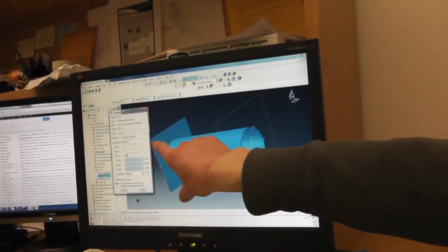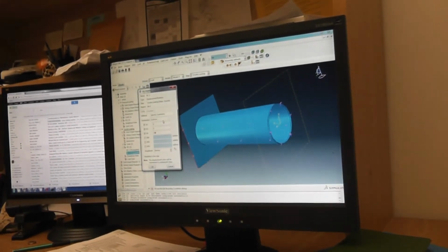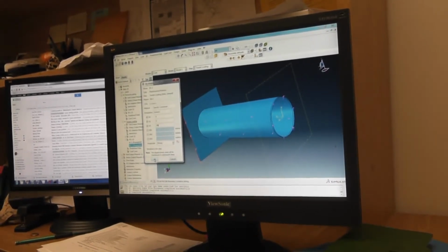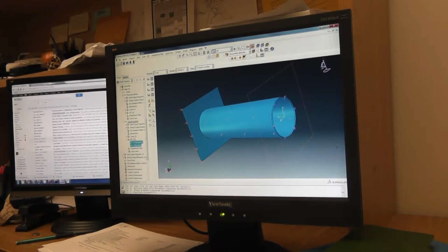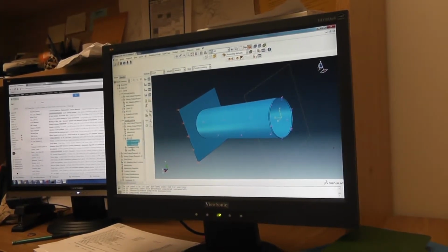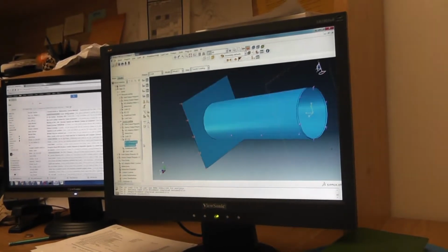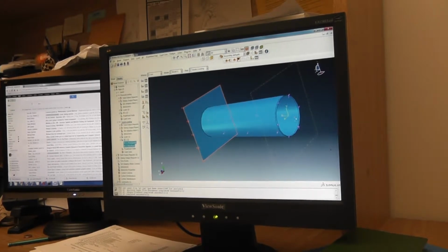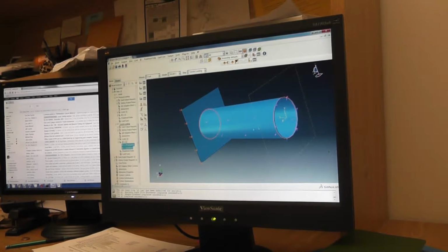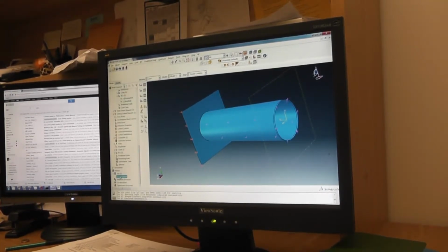Okay. So are you moving the plate? I'm moving the edge of the plate. In which way? In the Z direction. Tangent? Yes. Okay. And fixing U1 and U2. What about rotations? I don't need it, it looks stable because I fixed this in symmetry, because this is symmetric. Okay. So the symmetry stabilizes the model. Now let's run it.